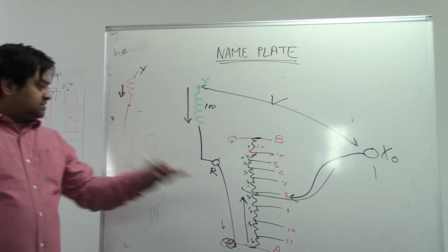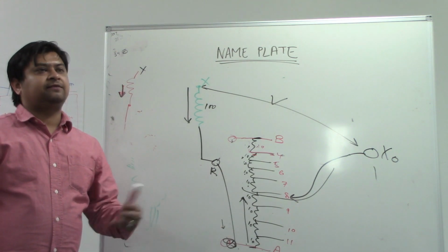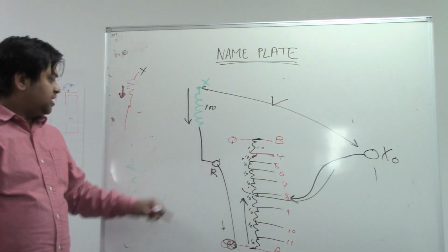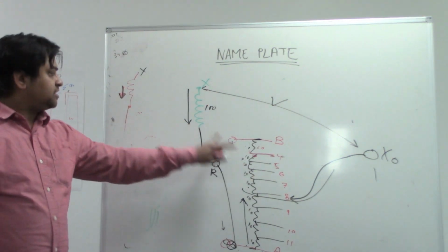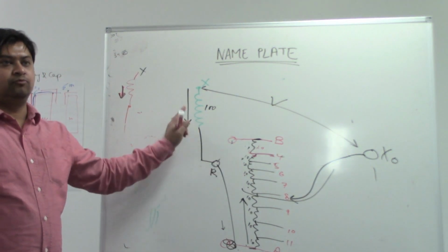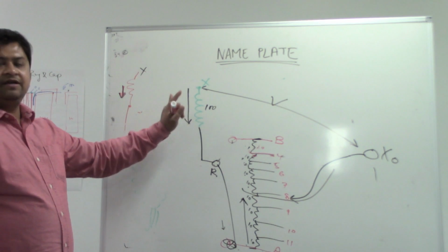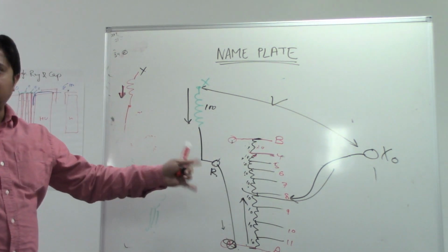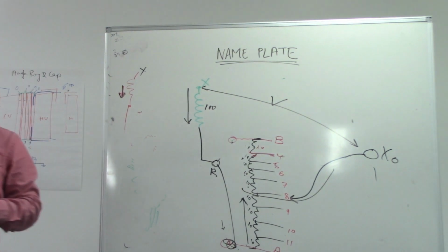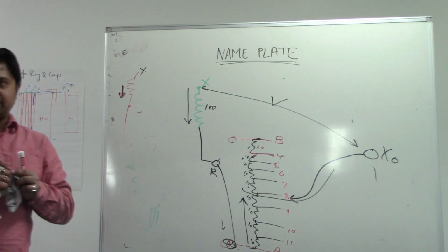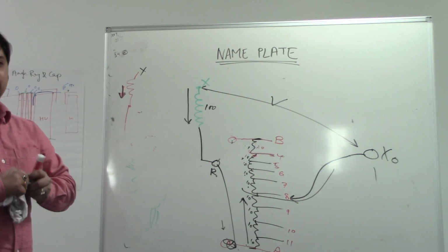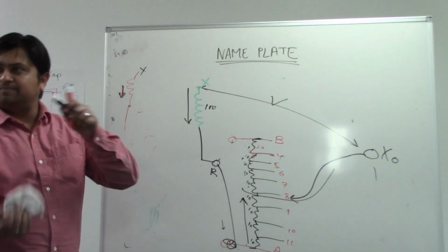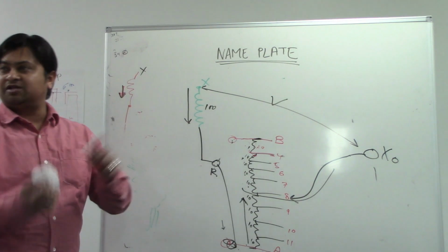Yeah. This is one of the methods. Another method is you can change the winding direction to change the current. Okay. So in this case we are assuming that the winding directions are same in both cases, for RB and for LB. But do you understand how we are making a plus and minus term? And when you are doing a physical ratio check in the HVA, when you are doing from A to B, B to A, how it is making a negative ratio, positive ratio.